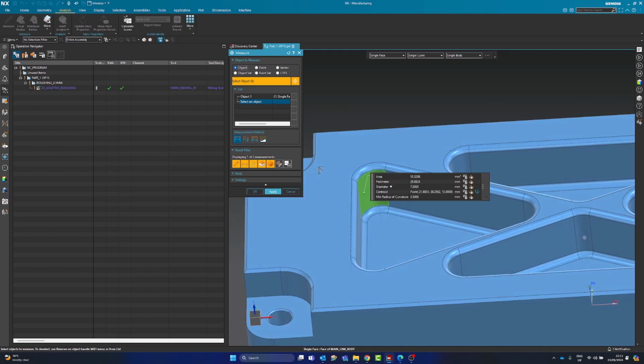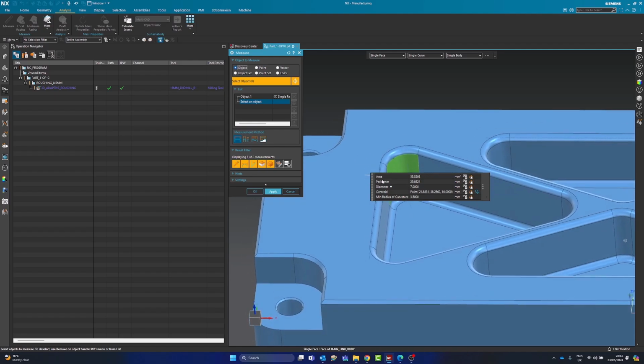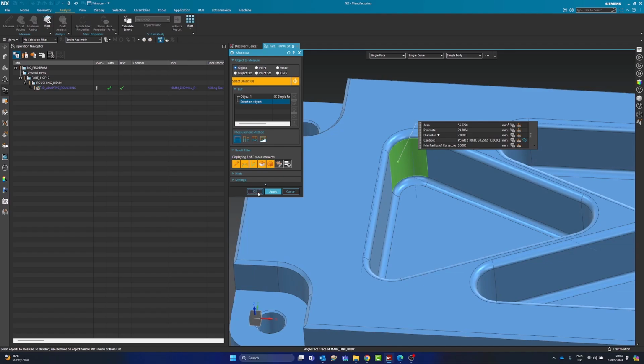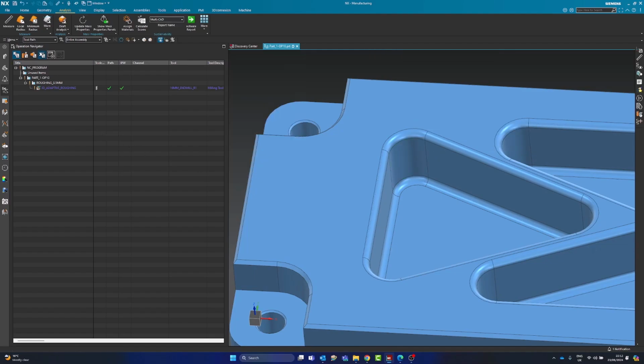And I mean, ideally, a 6mm cutter might be a little bit too big, because one thing you've got to think about is, yes, we're using a 6mm cutter, but we're also applying 0.5mm stock. So we're really not allowing the tool to move much in this corner. And this is where the minimum curvature radius comes in the adaptive toolpath, what I was just talking about. Let me show you what a 6mm tool would do in this corner here.